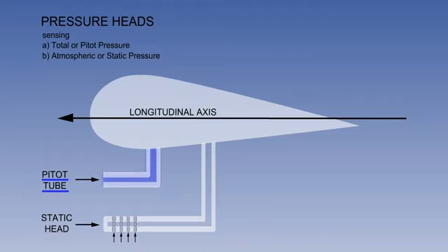A pitot tube usually consists of a head on a strut or a tube on the nose. It is fixed parallel to the longitudinal axis of the aircraft to ensure that the full dynamic pressure is sensed. The air can either be brought to rest inside the pitot tube against a stagnation wall, which is simply a pressure measuring flat surface, and then transmitted up the pitot pipelines to the user instruments, or it can be passed directly up the pitot pipelines.